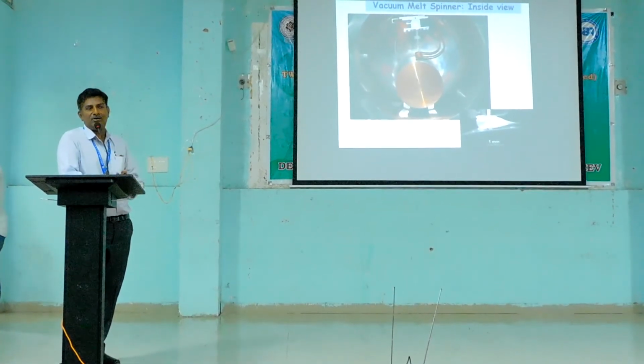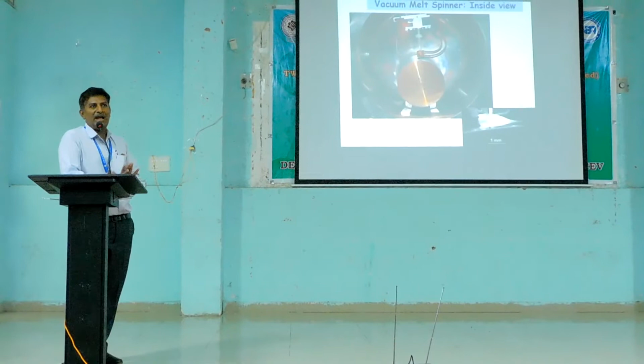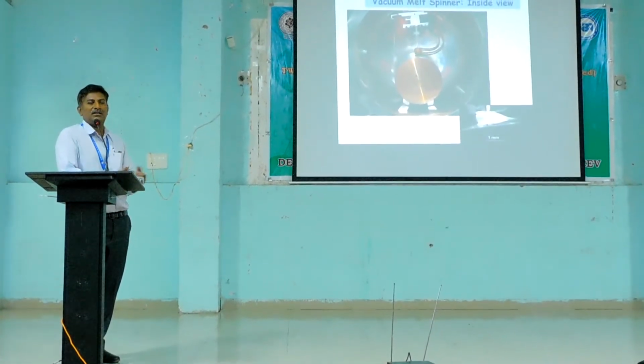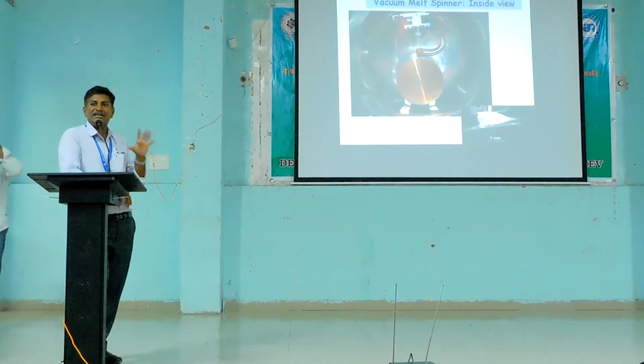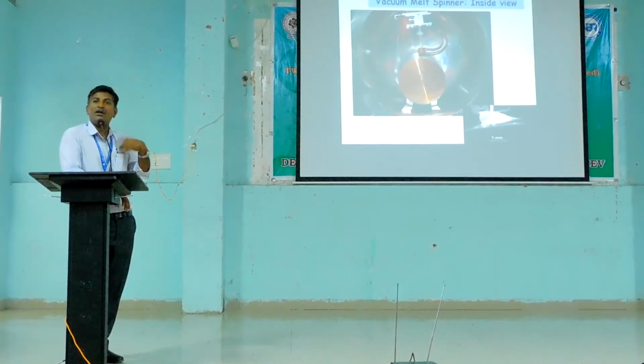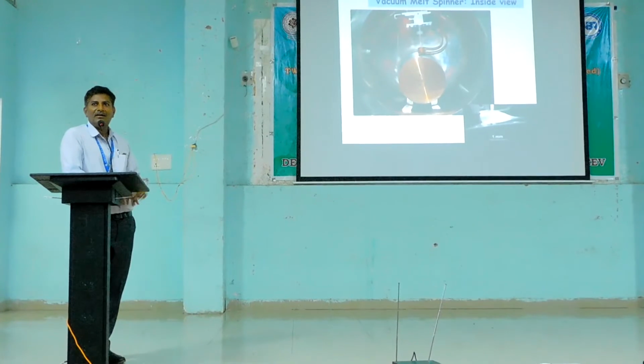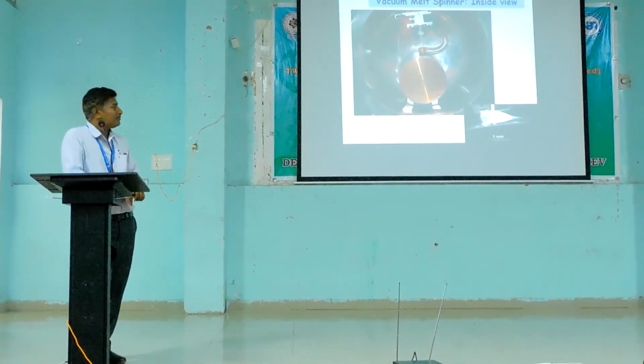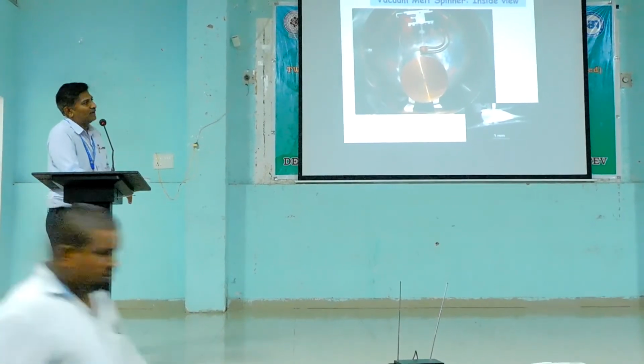So the first thing you have to know when working in a lab and you want to melt these alloys is that it has to be done in vacuum or inert conditions, that is, in an argon environment or nitrogen environment. So we generally do it in vacuum.